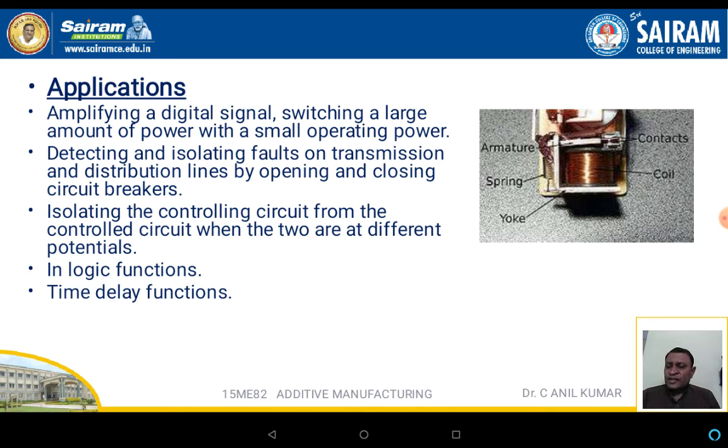The applications of the relay are amplifying digital signals, switching a large amount of power with a small operating power, and isolating the connecting circuit from the control circuit when the two are at different potentials. In logic functions and even in time delay functions, relays are used for switching on and off.